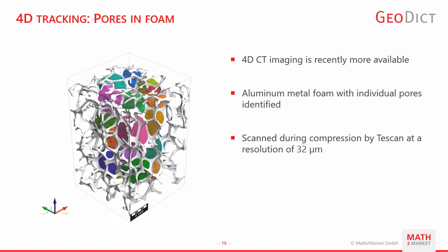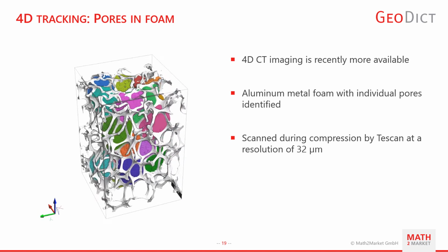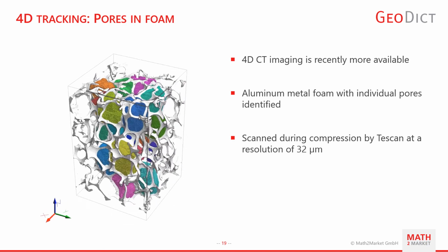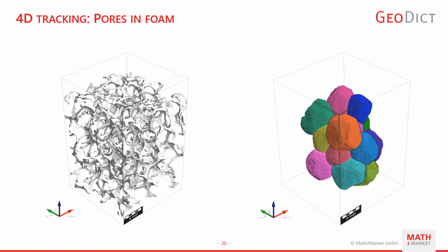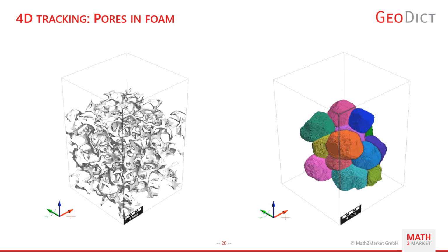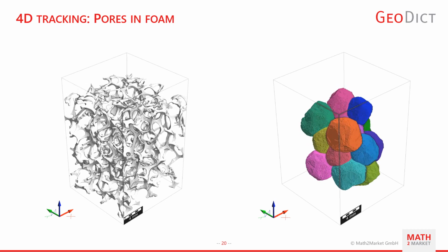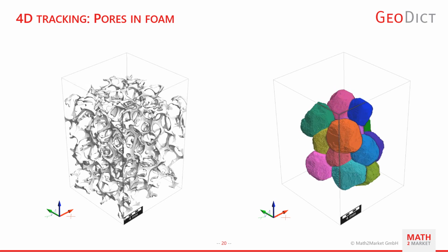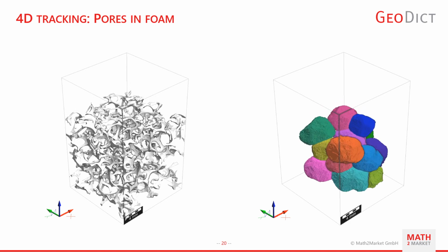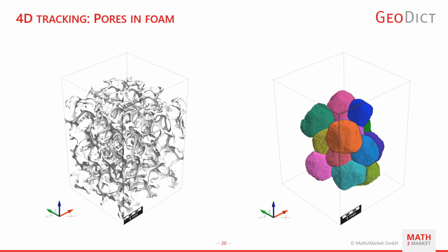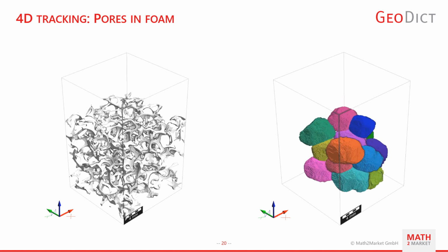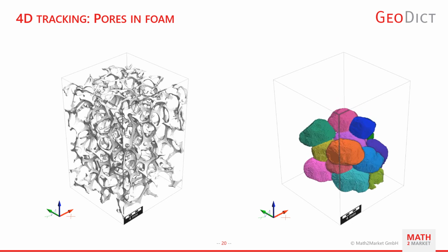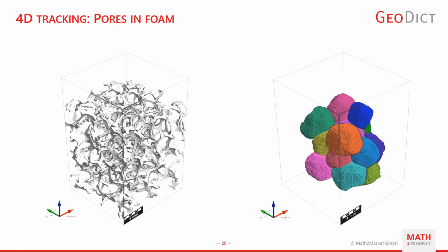That scan was done by TScan at a resolution of 32 micrometers, while the foam was being compressed. So here it's not compressing yet. Here you can now see the foam compressing during the imaging process. It was a continuous process, there was no stopping in between. On the right side you can see the pores from the slide before. We've identified them in each frame of this compression and tracked them throughout the whole process. So we can now see the deformation of the pores and, for example, also analyze this.